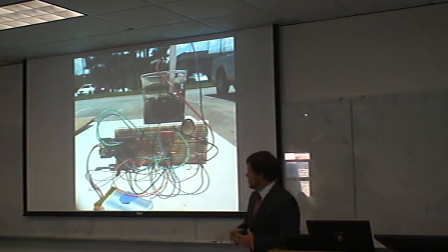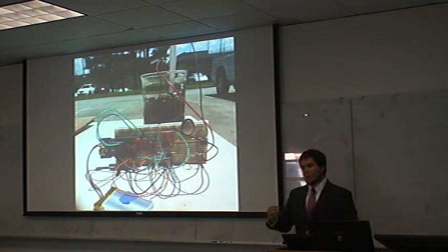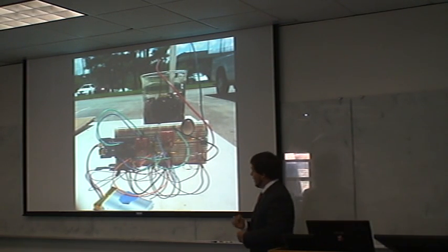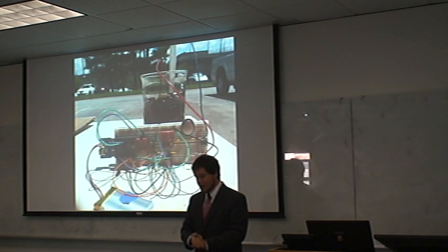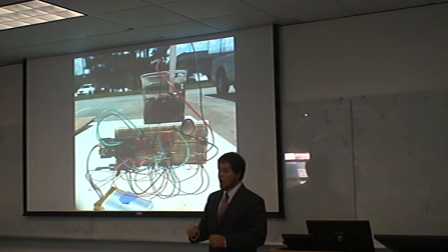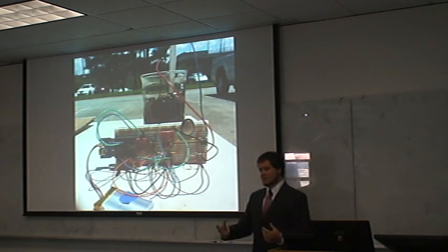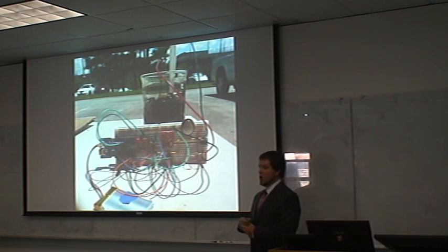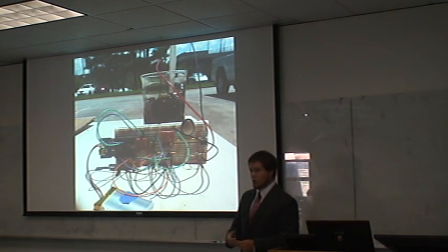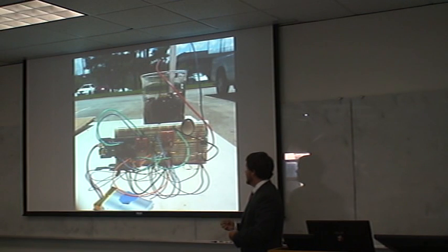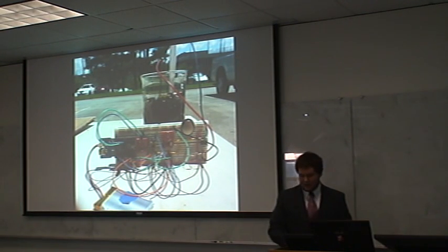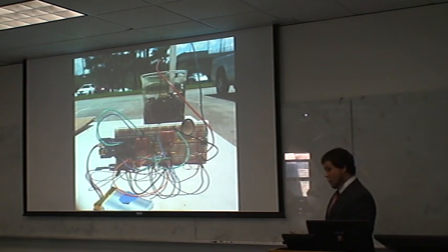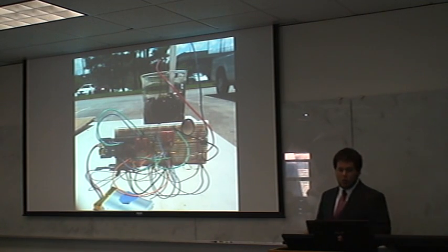And again, all that's doing is saying, is there water in the soil? It's not saying how much water. The soil moisture sensor and the leaf wetness sensor, those 2 are relative sensors. You're saying, okay, yes, there is water in the soil, or yes, there's a lot of water in the soil. You're not saying there's this much or that much. And with the leaf wetness sensor, you're saying, okay, there's some water on the leaf or there's not water.